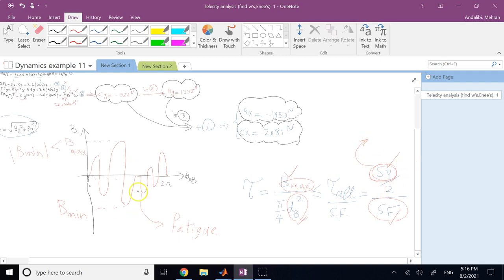In some materials, the more that you apply this dynamic, variable load on the object, if you look at the strength versus the number of cycles, where N here is the number of cycles, for some materials it just keeps going down until it reaches 0. For some other materials like steel, it goes down until after so many rotations it goes to a constant level, which we call the endurance limit, SE. Then using that SE, the number of cycles and so on, you will design for your pin, which we call fatigue design. There are different methods like Goodman and so on. There are 3-4 methods that you can use for fatigue design.